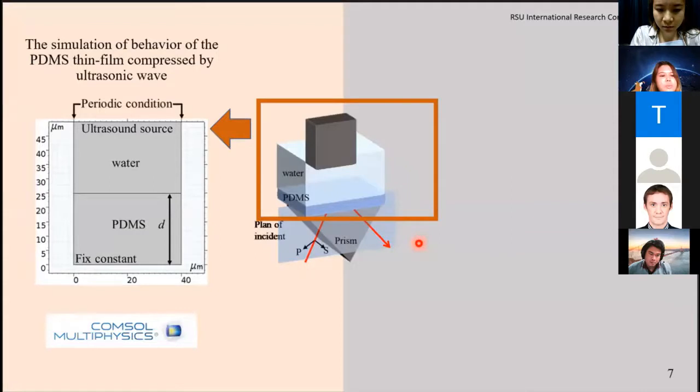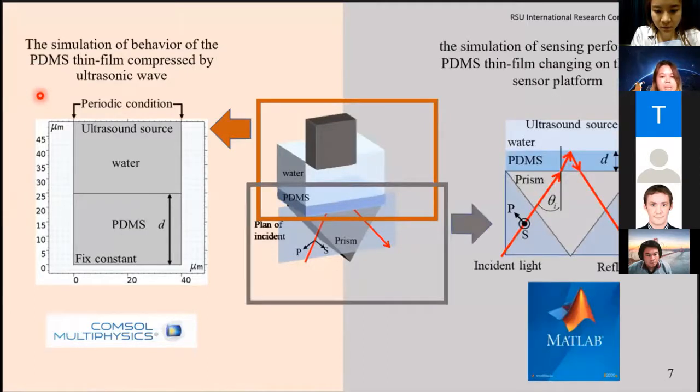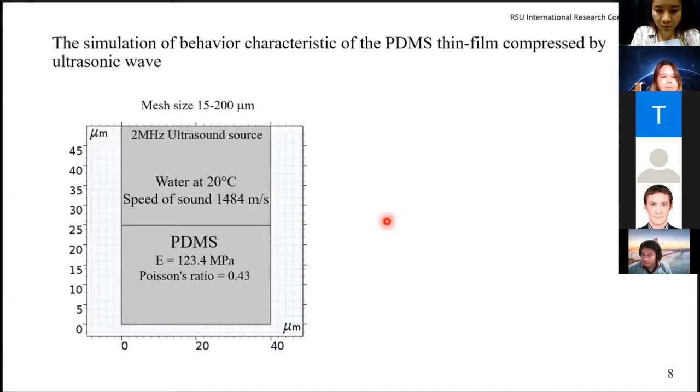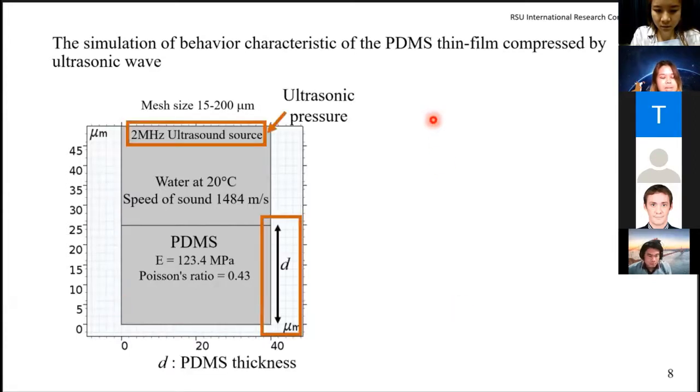For this work, the simulation of the behavior of the PDMS thin film compressed by ultrasonic wave was calculated by the finite element method on the COMSOL program. And the simulation of the sensing performance of the PDMS thin film changing on the optical sensor platform was calculated by the Fresnel equation in the MATLAB program. This is the study model on the COMSOL program, and these are the parameters set in this simulation. In this simulation, we study the effect of the acoustic pressure and the thickness of PDMS thin film.